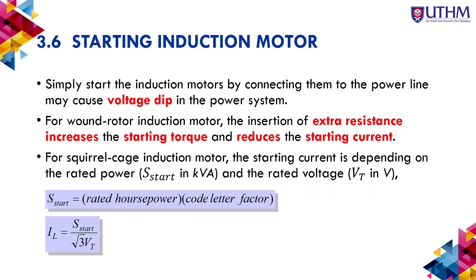Okay, so now we will continue the induction motor with the 3.6 subtopic. This is the starting of the induction motor. We can directly connect the induction motor by connecting it to the power line. However, it may cause a voltage dip. Suddenly the voltage will drop.